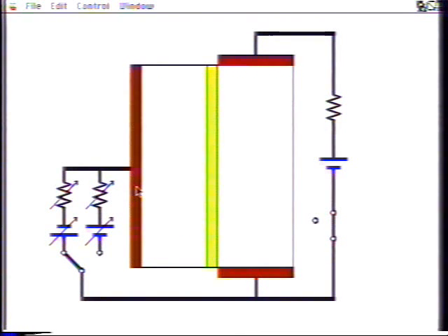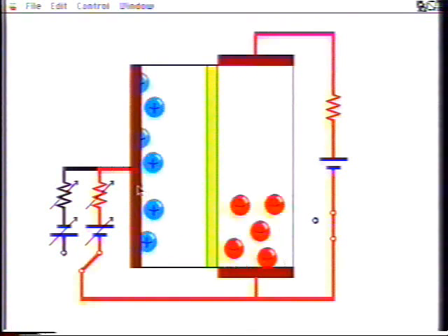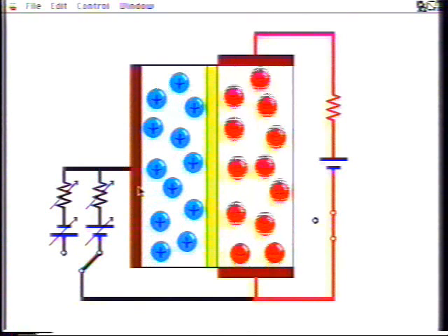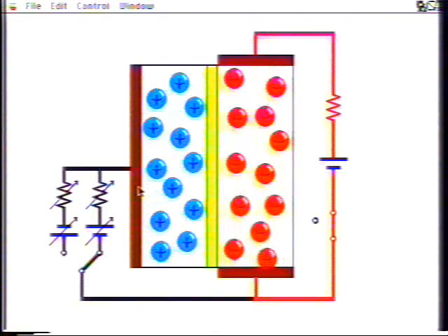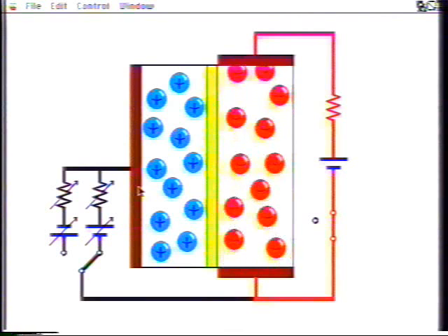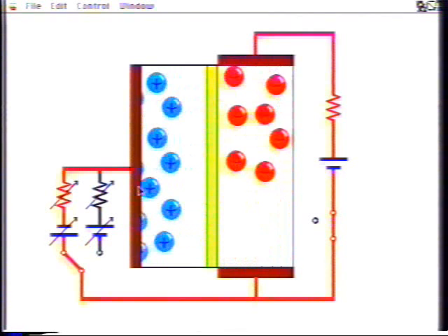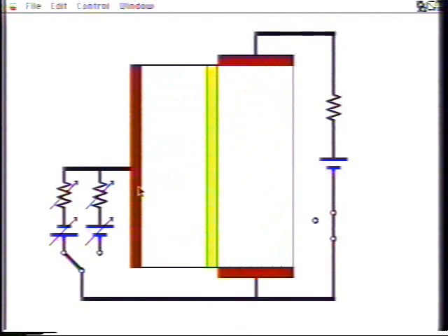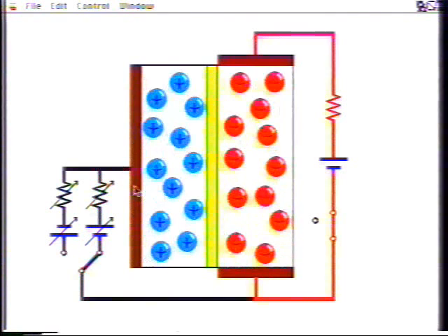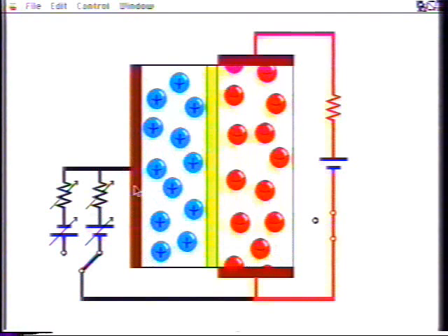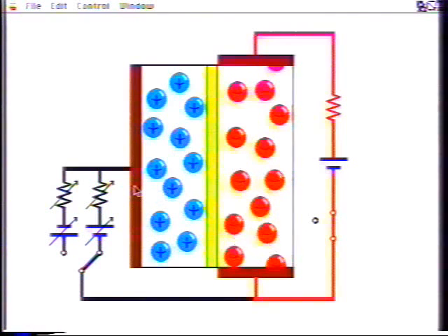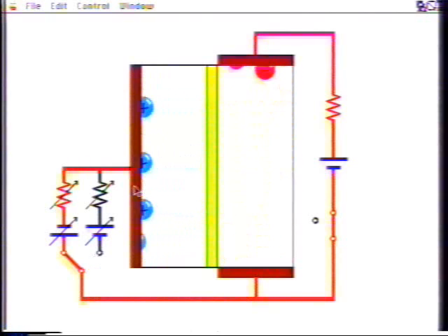If you want the switch to close faster, you have to stuff the gate charge in faster, requiring a larger transient gate drive current. If you want the switch to open faster, you have to yank out the gate charge faster, requiring a larger transient gate reverse current. Thus, for fast operation of the switch, the gate drive must be able to both source and sink sufficient current.